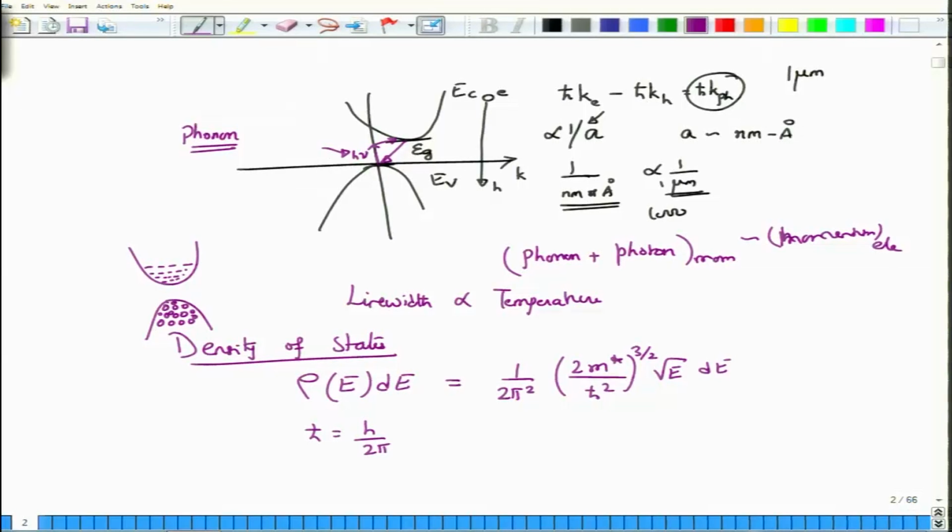Of course, you might ask where is the semiconductor in this equation. The semiconductor part of the input into this equation comes because of this m star. This m star is called the effective mass of the carrier. If it is an electron, we would write this as m star E, and we would write m star H for the holes, and it turns out that the electron effective mass is far less compared to the hole effective mass.